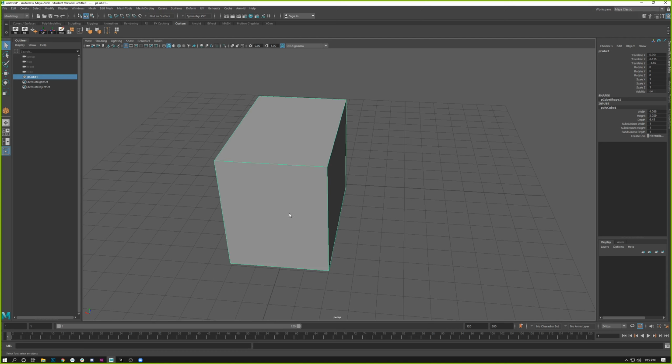Now, in Maya, after you've created an object, what you can do to access these is right-click and hold on an object, and you can go into Vertex mode. So I'm right-clicking and holding, getting this marking menu, and if I hover over anything in here, when I let go, it will access that part. There's also a huge drop-down list of other things in the future that we can mess with here, but this top part is the subcomponent mode. So if I right-click and hold over Vertex and let go, it will enter Vertex mode.